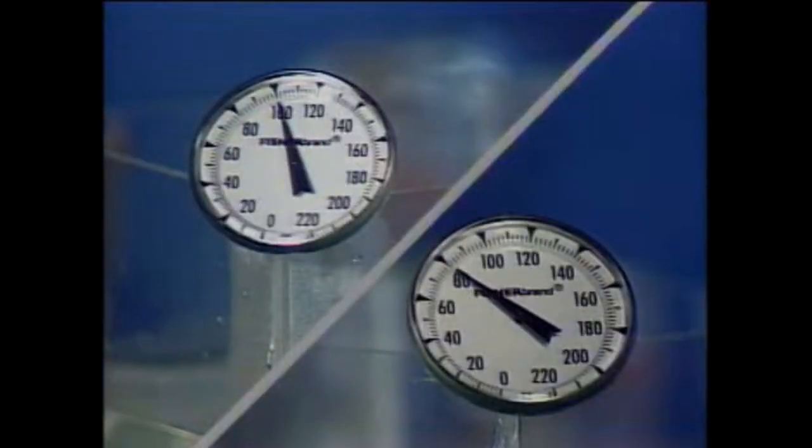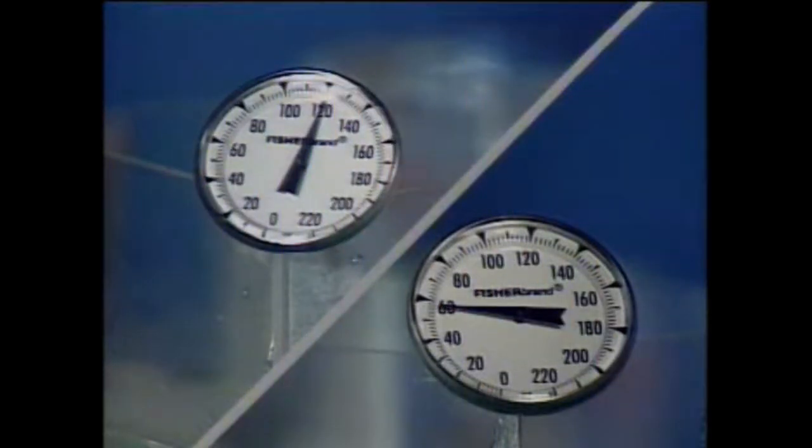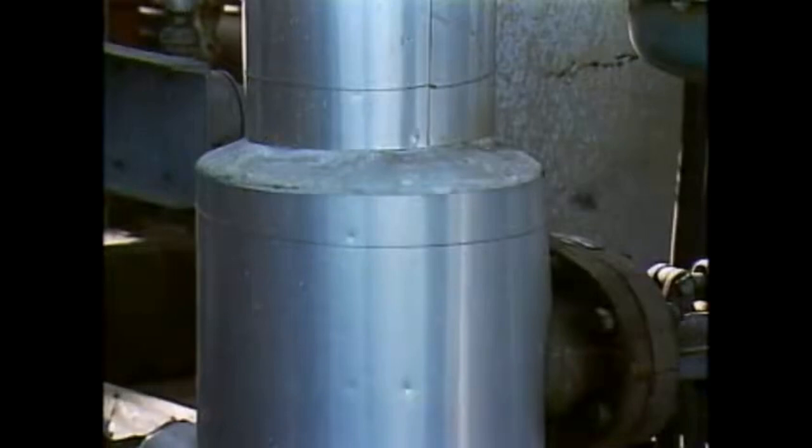For example, as the difference in temperature between the two fluids in a heat exchanger increases, the amount of heat that can be transferred also increases. The amount of surface area in a heat exchanger is another factor that affects heat transfer. Basically, the greater the surface area, the greater the amount of heat transfer that can occur. Another factor that can affect heat transfer is the type of material that the heat is transferred through. Materials that are more dense are better at transferring heat and are normally used as conductors of heat. On the other hand, materials that are less dense will transfer less heat and are normally used as insulators.